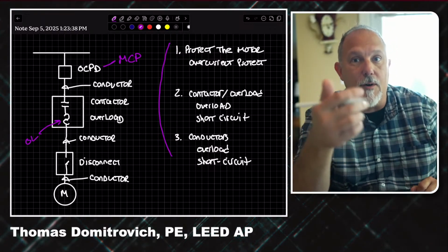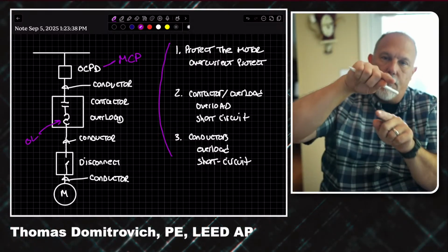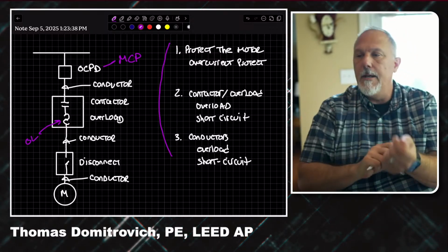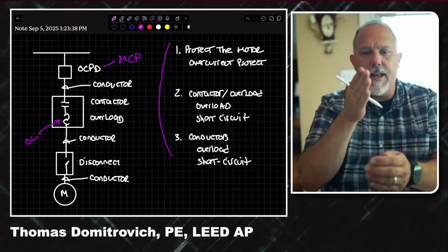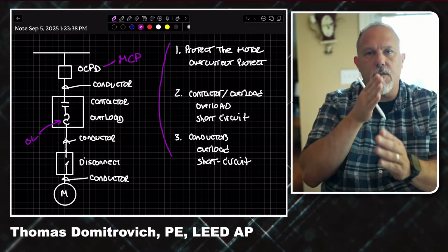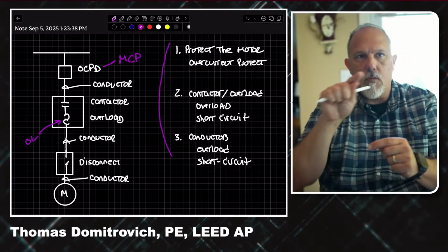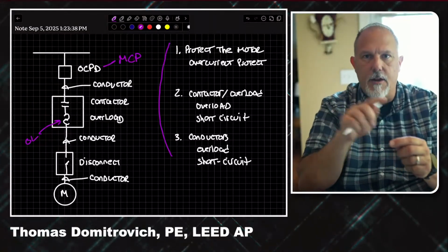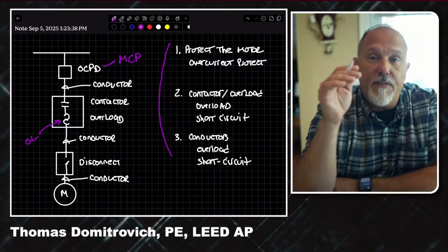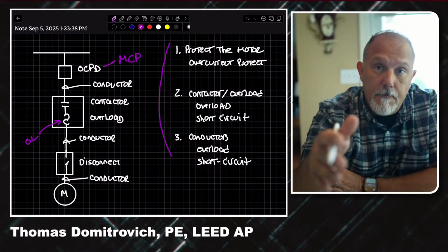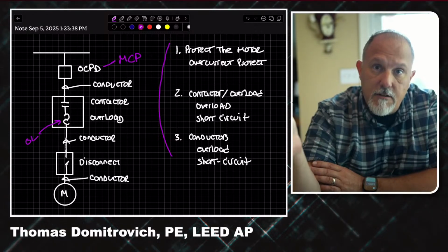And the Allen Bradley, the Rockwell ones, they were the little round white. They looked like little donuts. You put them in, and they had little ears on them. You'd put them in, screw them in. The Cutler Hammer ones that I remember on the Freedom Series starters, they had a flat, and when you took the overload out, it was like a little worm that was in there. The current was going through, and those units, when I worked at Crystal River Unit 3, I learned that there's a voltage drop across those because it's a resistance value.